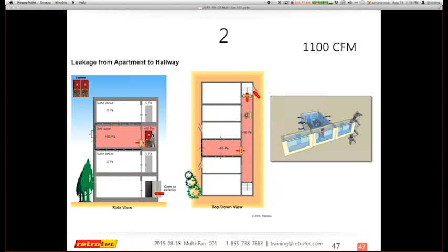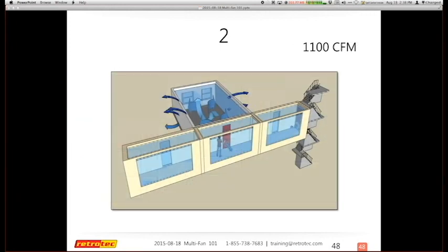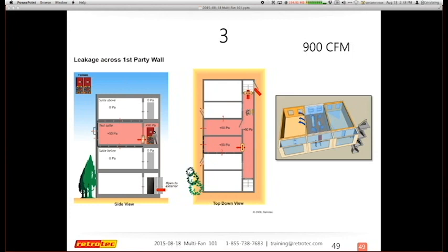And we'll continue this. So now, depending on how small they are and your fan, I can actually just open the door and let air move into the unit on the right side. Again, I have a pressure relief on the other. You can tell this would be a challenge for an occupied structure, in terms of asking somebody if I could open their door and let air blow through, and see if the neighbor next to them could allow me to open a window. So it does have its logistic challenges, but this is the practicality of actually doing this, and you totally appreciate what happens when you actually have a floor to yourself to do this kind of testing.